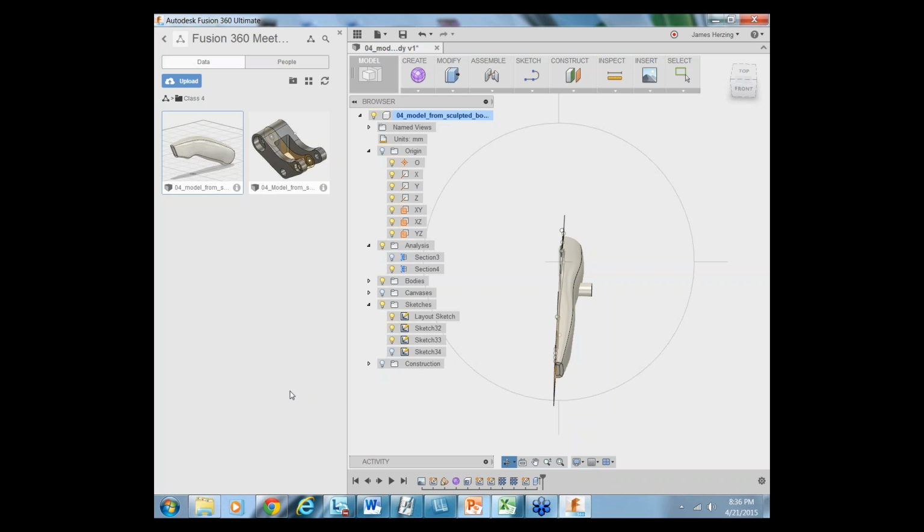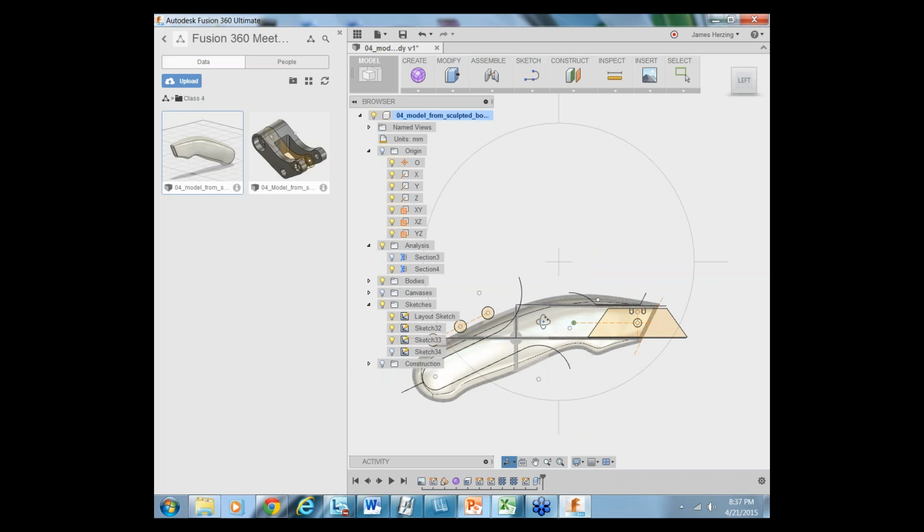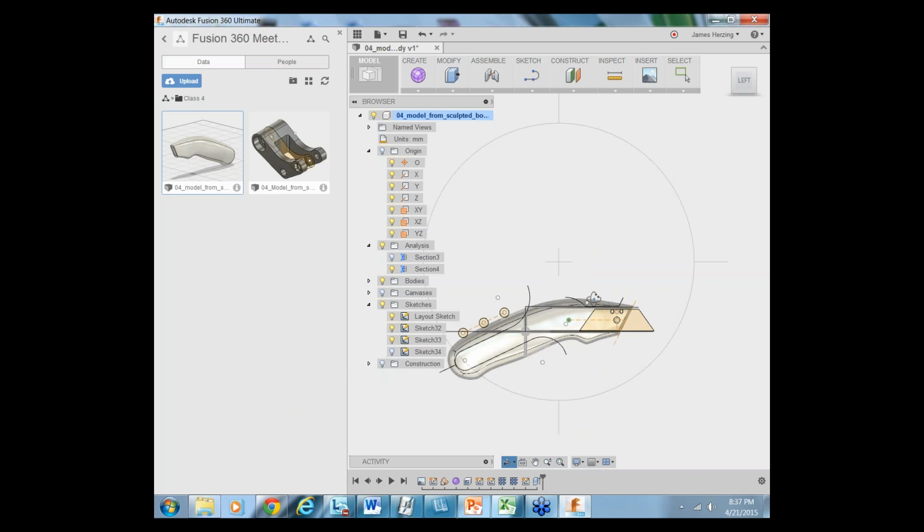I'm trying to select a circle, and I guess it's because of the curves here, do I have to drop the sketch? Because otherwise it chops it into pizza slices. You can use the shift key and select all of the pizza slices and then extrude it. Extrude to the other side, is that okay? Yep. Extrude symmetrically and you're good to go.